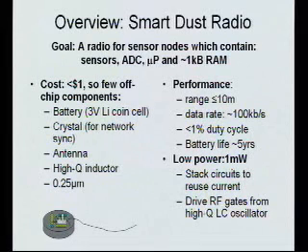So there's a few techniques I'll be hitting as I go through this on getting down to 1 milliwatt. One technique is to stack circuits so that your bias current gets reused over and over again. And the other trick is to use my one very high Q inductor to tune out as many capacitances as possible, so that I basically get a power reduction by a factor of Q.